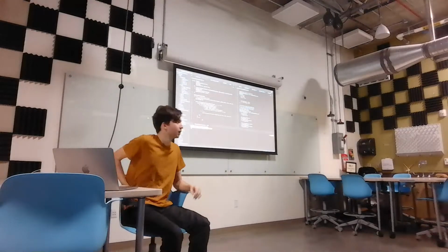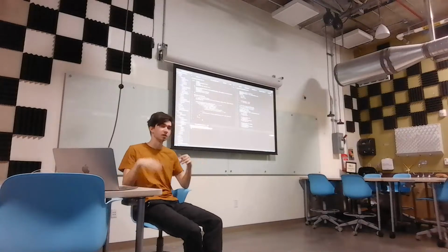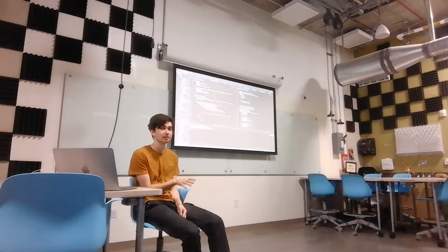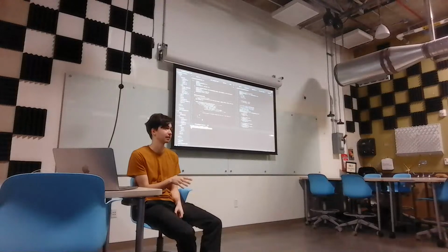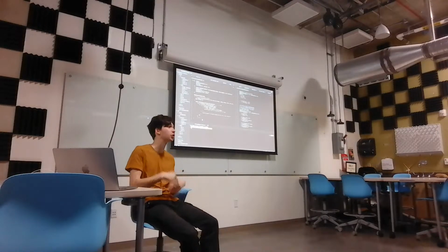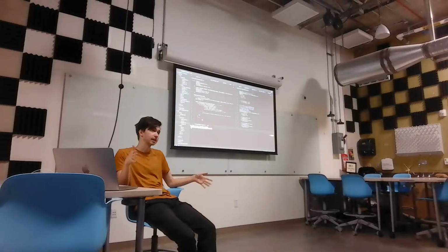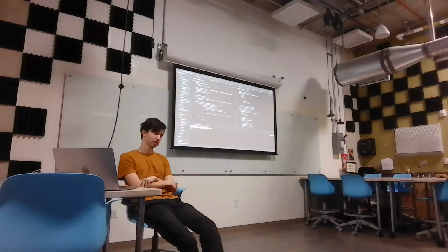Here's the thing though. When I looked into this, I learned that this Rust Bluetooth library was based on something called Embassy. Embassy is a Rust framework that allows you to do, you ready for this? First class async stuff on embedded. I can define functions that are async. I can await things. I can have multiple threads running concurrently, exchanging information in real time. The performance overhead is close to zero. Close to zero. In many cases, actually, it's faster than doing it yourself.